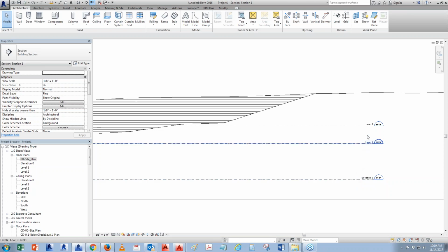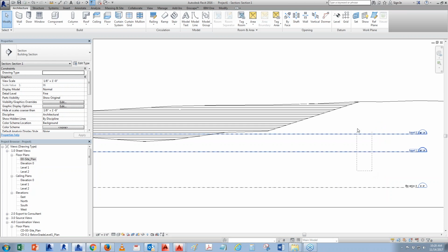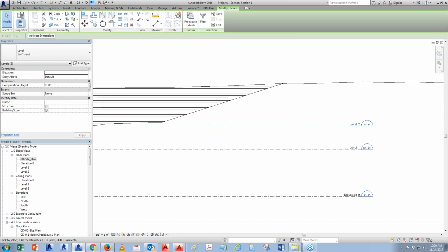Okay, if you place it into level 1, level 2, what it does is that it always offsets. So I typically don't do that. So that's the trick. If you have a camera that was screwed up, or someone deleted the camera and you want to recover it, elevation 0 is going to help you with that. Okay, just a trick. Okay, so let's say I'm going to move this up to 40 feet.